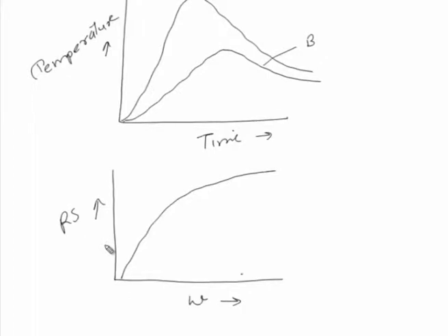So, if we can see here, on the x axis we have the amount of weld metal being deposited, and on the y axis we have the residual stress being developed. With the increase in the volume of weld metal deposited per unit length, there will be a continuous increase in the residual stresses. Further, let us see how the residual stresses develop in the different directions, in the transverse as well as in the longitudinal directions.